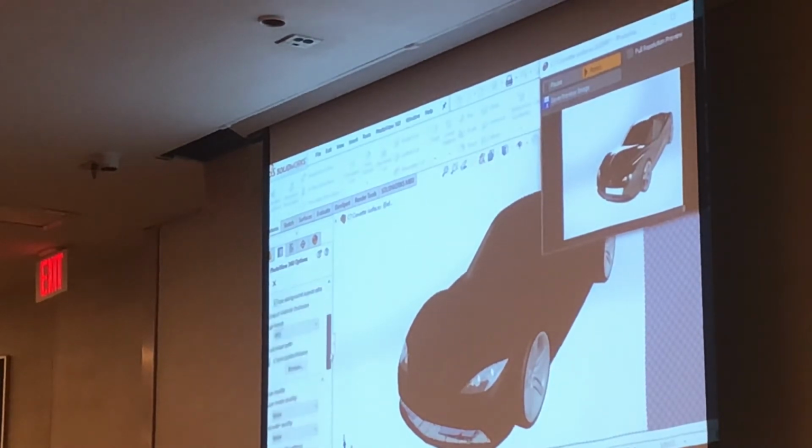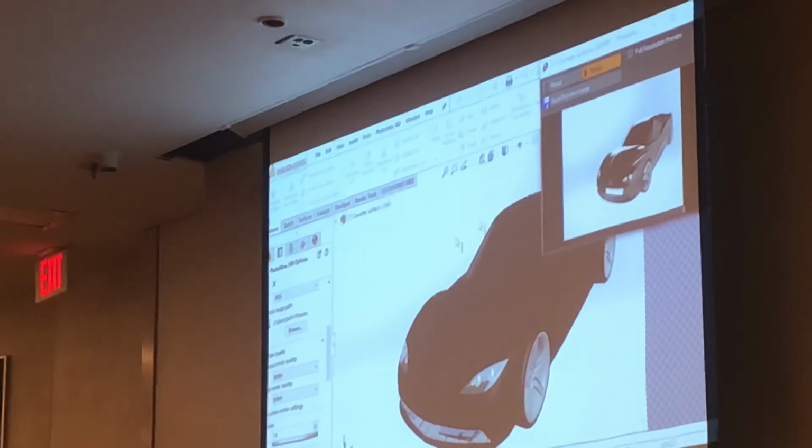And then down below that, there's a section for the render quality. You can set the quality for the preview window as well as the final render that we're going to produce at the end. Your options are good, better, best, and maximum. So this setting determines how many bounces a ray of light or a vector is going to take before it just stops calculating.